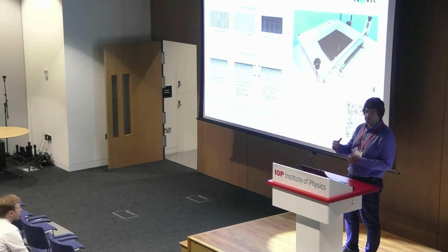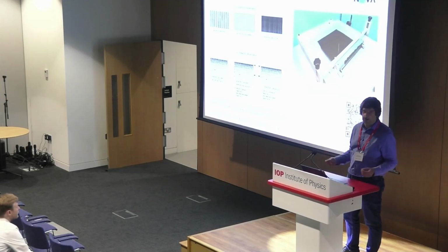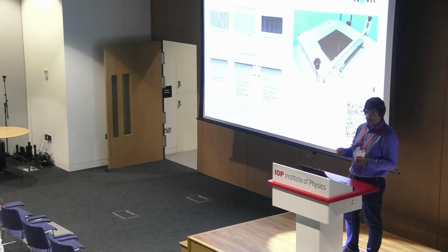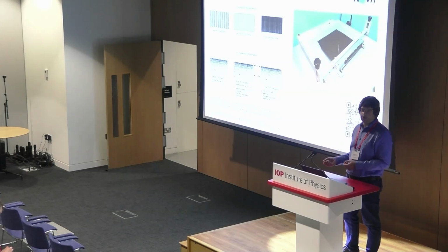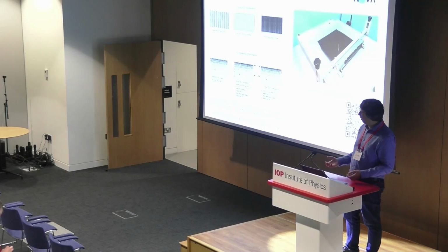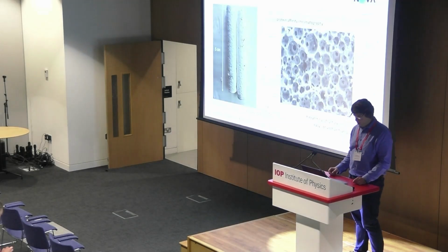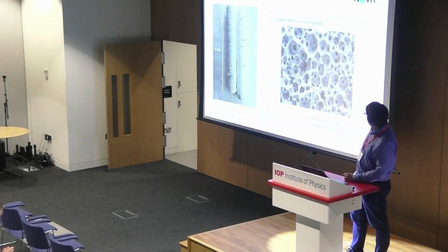And the membranes might have different structures. They can be symmetric, they can be asymmetric, they can have pores, they might be dense. So, basically the structure of the membrane and obviously the material of the membrane strongly influence the mass transfer through the membrane. Therefore image analysis is so important for us in order to understand the structure of the membrane, how the pores are interconnected, what the possible pathways are for the transport of species through the membranes.